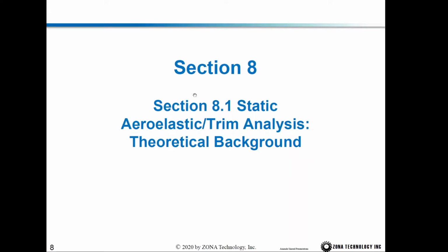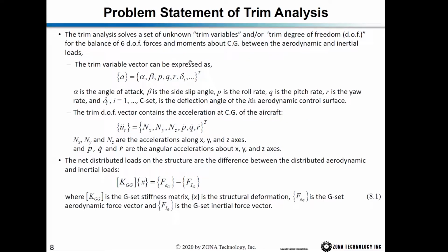Section 8. In this section, we're going to talk about static aeroelastic and trim analysis using the trim module of ZAERO. The trim analysis solves a set of unknown trim variables and/or trim degrees of freedom for the balance of the 6 degrees of freedom forces and moments of our CG between the aerodynamic and inertial forces.